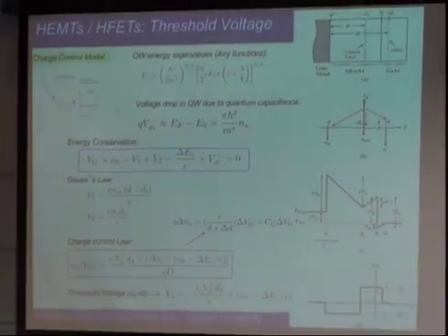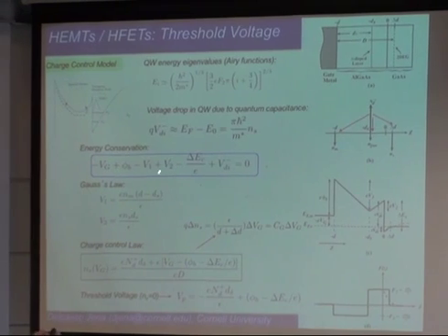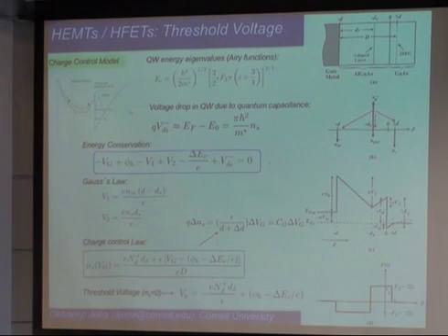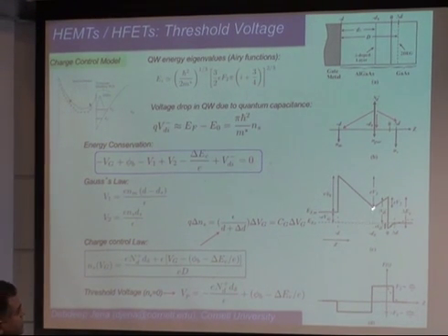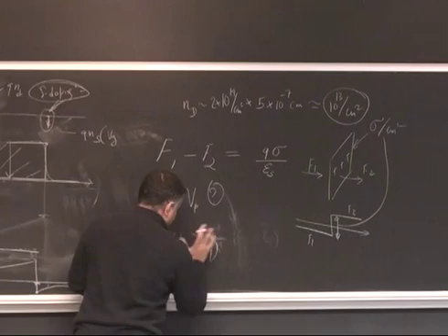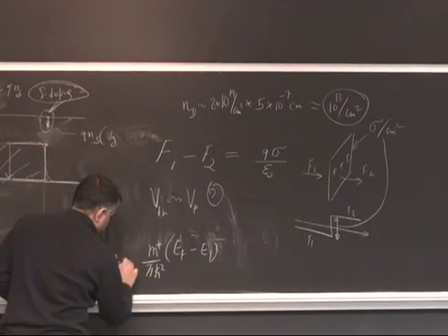Make sense? Yeah. Then you go back up by V2, and this is not the pinch-off voltage, but for any gate voltage, this is the situation. That's what we're doing in general, right? So we go back up, and the voltage there would be just field times distance again, and then you reach there, and remember, you go down and then you have to come back up to the Fermi level, and for that little window you use this EF minus E1 times m star by pi h bar squared, density of states times the energy bandwidth, is equal to ns roughly.